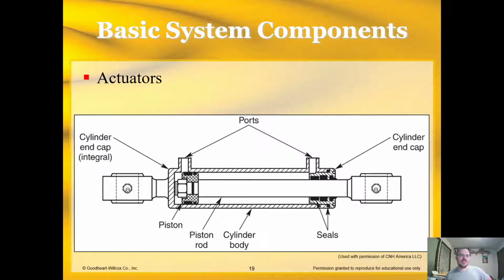So here's another actuator. Your cylinder actuator, what is it created of? We'll go into a bit more when we get to the chapter on actuators. But basically you have 2 ports, and it's kind of like the other one, except this one's linear actuation rather than rotary. We put pressure on this side. Pressure fills this chamber, pushes against that, and this is free floating, so it can slide. All the fluid that's in here gets pushed out and goes back to the reservoir, and this extends, and vice versa to retract it. We'd have high pressure in here to retract, and anything that was left in this side goes back to the reservoir.